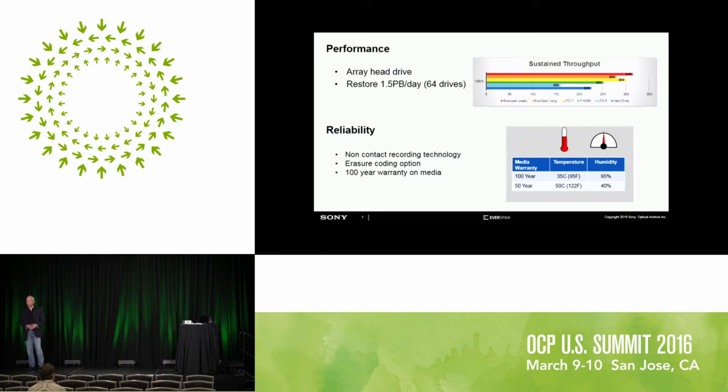The optical technology is a non-contact recording method. So that means the head is never in contact with the medium. What that means is you can read from this medium as often as you want, and you can load this medium into a drive as often as you want. The reliability of the medium is not impacted by that. This is much different from tape. A tape you can only load so many times into a drive. And with tape, also with hard disk, there is a defined end of life. If you use it, if you read it, you reduce the life of the medium. You don't have that in optical.